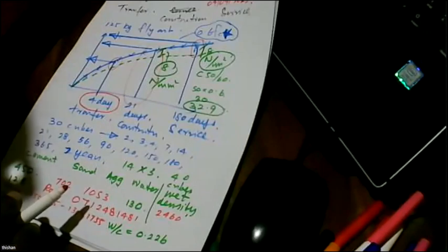So for that, you can have a different check, as long as you are sure that the concrete is going to gain strength. And how we ensure that concrete is going to gain strength is by using fly ash as an additive.